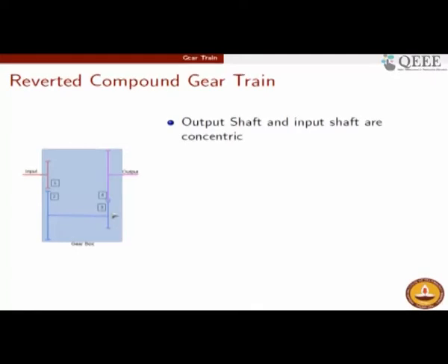and this goes and feeds into the wheel. Here we have another shaft called the lay shaft, and this shaft is parallel to the input and output shafts. You have two gears mounted here, indicated as gear 2 and gear 3. First there is a gearing between gear 1 and gear 2, so you attain a gear ratio between gear 1 and 2.